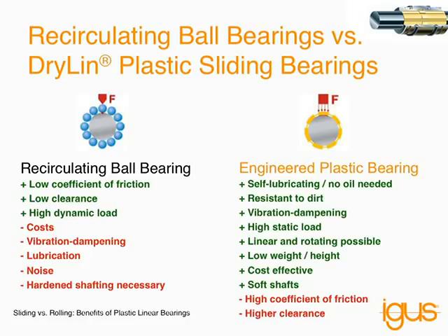Some of the negatives is that they can be cost prohibitive for some applications. They have problems in vibrations. They do require constant maintenance and lubrication. They can be loud, and they must use hardened shafting.